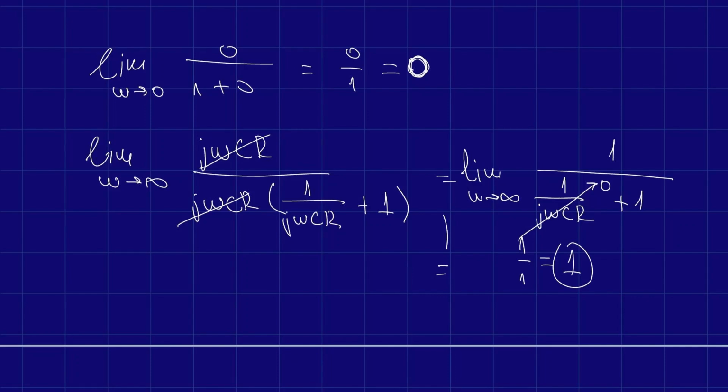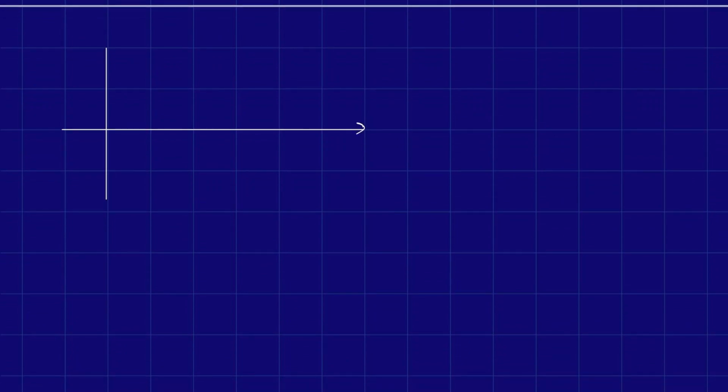Now, an important part of filters is also knowing how to design them. A very simple way, which is not used frequently, is to have the frequency on the x-axis and the gain on the y-axis, which is the same as saying Vout divided by Vin, okay? And we draw something like this. So here it means that at low frequencies the signal doesn't pass, and at high frequency the signal passes.